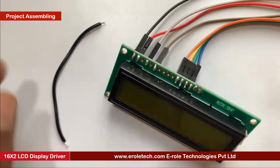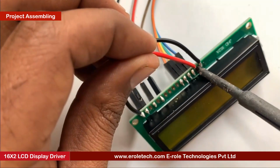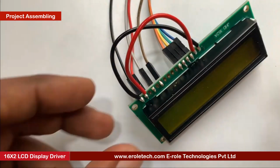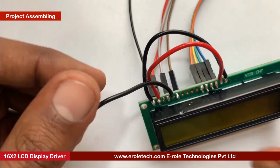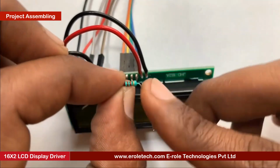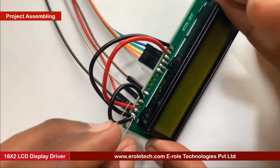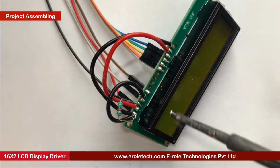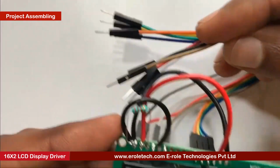Now connect hole number 16 with hole number 1 using a black wire and hole number 15 with hole number 2 of LCD display, using a red wire. Now connect hole number 5 with hole number 1 of LCD display, using a black wire. Now connect hole number 3 with hole number 1 of LCD display, through a 1 kilo ohm resistor.